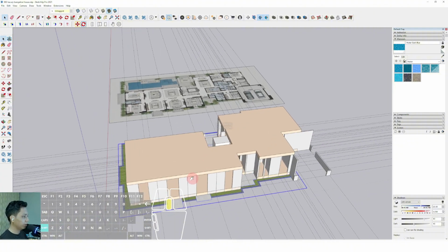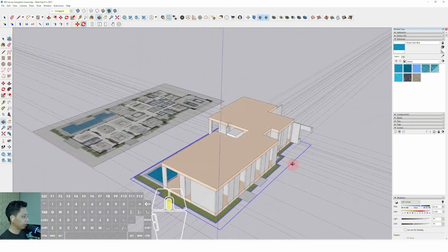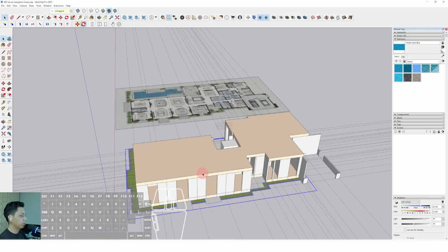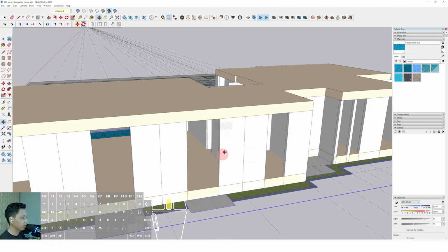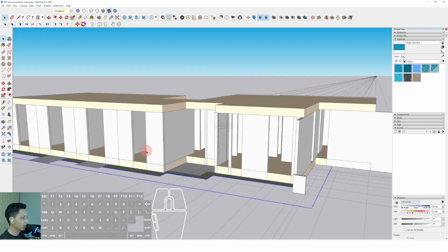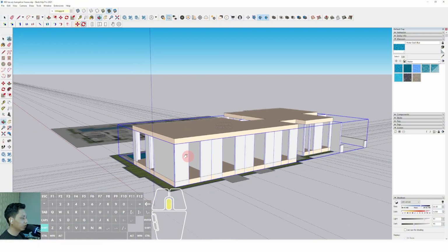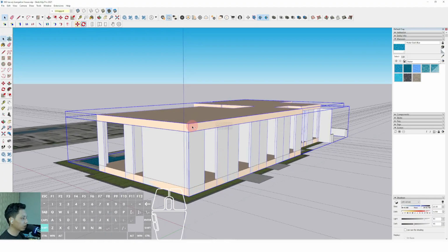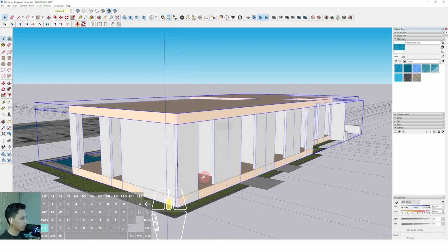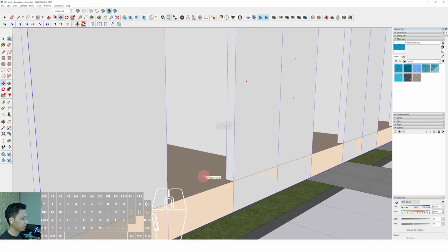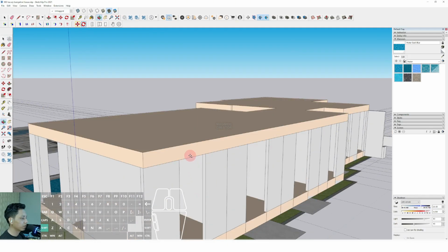Okay, now we can continue to make the other elements for the first floor, because we have already made the ground floor 3D modeling, and now we can duplicate this wall and also this slab to the first floor. We can select move, click the surface on the top of the finished floor on the ground floor, and move it up until this position.